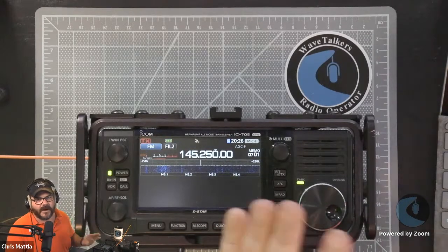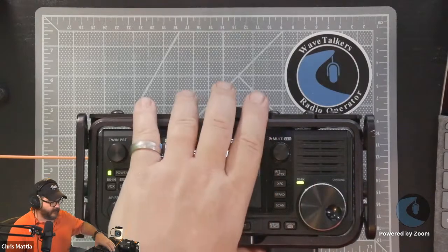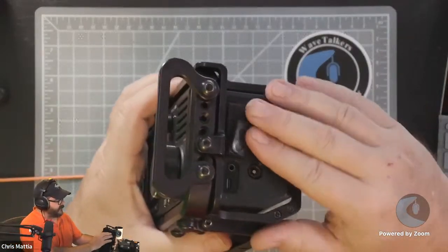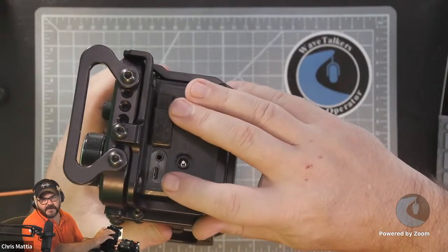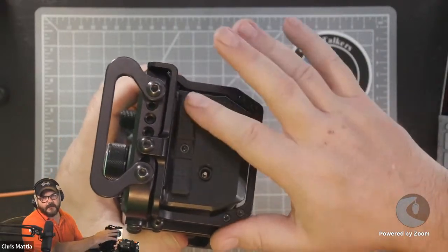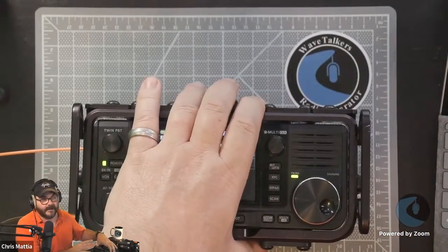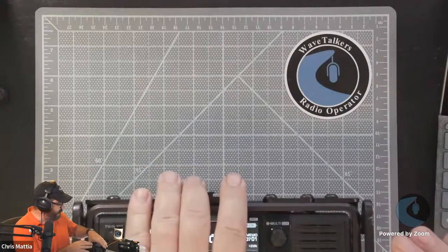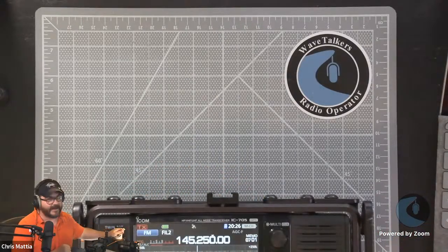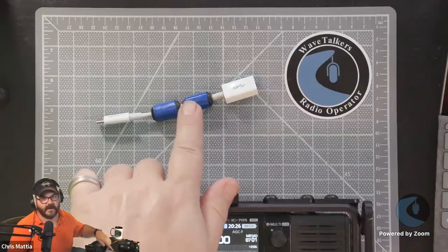However, that's rarely what I have found to be the problem. The problem usually stems from your USB connection. Now, I've updated mine. I have the USB-C port on here. I updated this entire board inside of my radio. It works great. Love that board. The problem that I've seen with the 705 with the transmitting is RFI getting into the connectors from the computer.